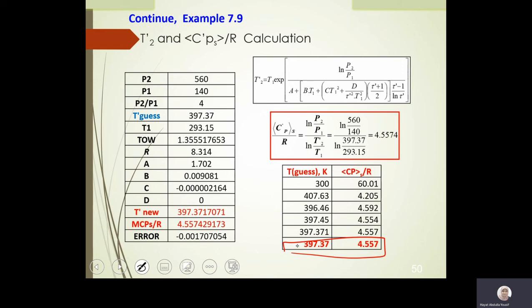To get delta HS, at this T1 and P1, you will go to the table and get H1. You will need S1 because S2 prime is equal to S1. You will also need to know the volume, and I will tell you why. Remember, in the previous equation, we said that to calculate W isentropic you need the specific volume. So at 45 degrees C, which is the inlet, at 10 kilopascal, it was saturated liquid, so we got the volume of the liquid.